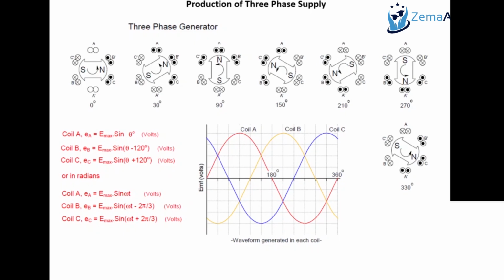from the single phase supply, the instantaneous voltage, meaning the voltage at a particular instant on a sinusoidal waveform, is equal to the peak voltage times sine of theta. If it is angular, the instantaneous voltage is equal to the peak voltage times sine of 2 pi ft. F is frequency. Sorry, t is not time period. t is the time at which you want to calculate the instantaneous voltage. So that was when we did the single phase system.